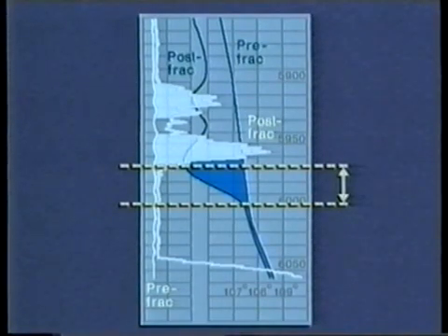All of the techniques discussed so far, temperature surveys, noise logs, and radioactive tracer logs, help us to qualitatively determine the entry point of fluids, the existence of channels, and the location of injected materials.